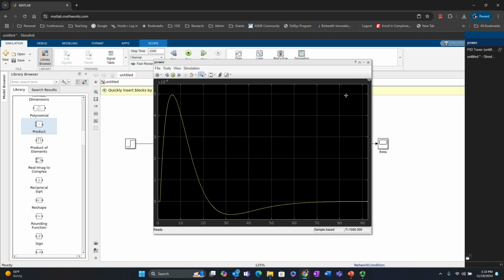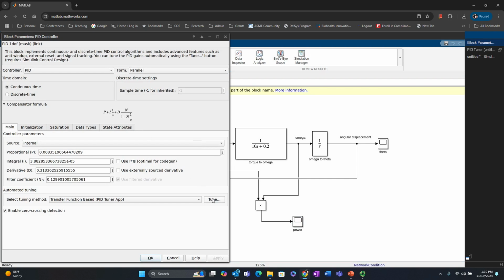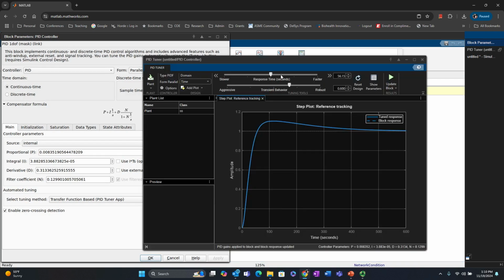And all right, obviously this is a very slow operation, right? It takes 600 seconds. It takes 10 minutes to sweep 60 degrees. And now we are wondering, all right, what's going to happen if I want to be really aggressive? Why don't we go and find PID controllers that will give us a more aggressive behavior? So let's look for a response time that is much, much faster. In this case, it gives me 13 seconds, 11 seconds, 9 seconds. Okay, let's say maybe 10 seconds, right? About, let's say, settle around 10 seconds, and so that is significantly faster than the 600 seconds that we had before, right?